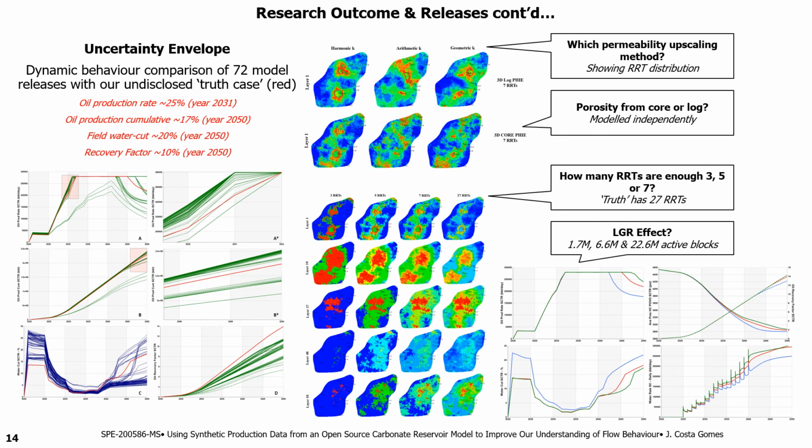As I had mentioned, this reservoir is very large, but you can even make it larger by reducing the grid sizes in X and Y. In this case, we have 250 meters by 250 meters, but if you were to use 125 by 125 or 62.5 by 62.5, you then increase your reservoir from roughly 1.7 million to 22.6 million grid blocks.